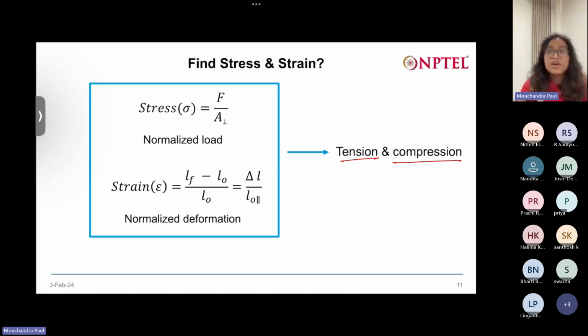then you cannot do that, because the forces acting on a sphere are different from those acting on a cylinder. That's why we use normalized quantities like stress and strain. We don't compare the forces or the change in length of objects of different geometry.